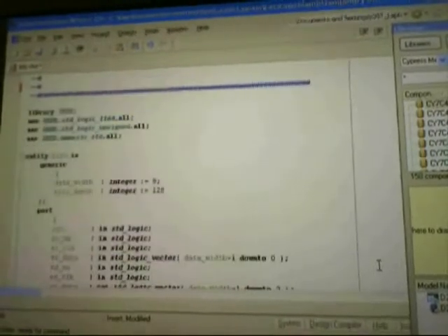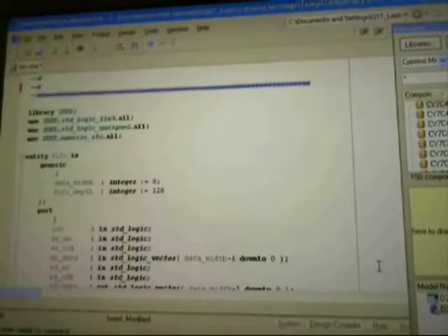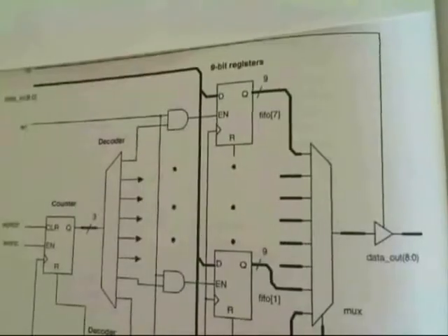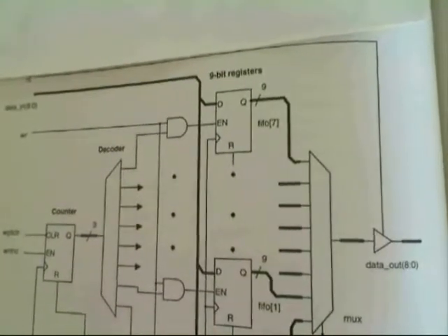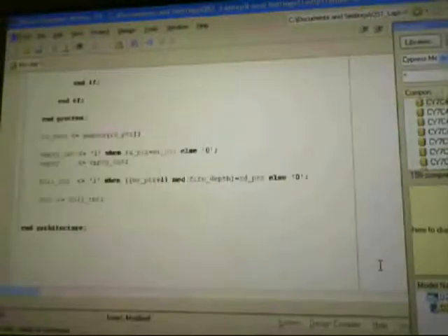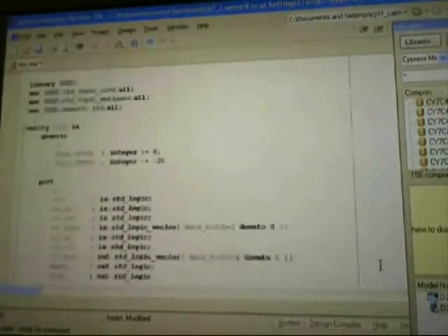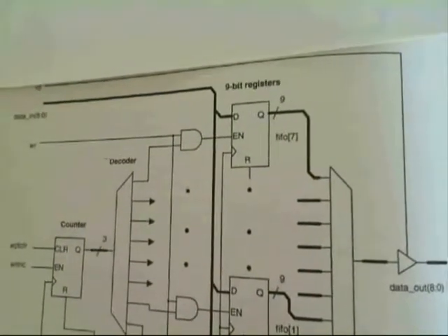The FIFO core provides an optimized solution for all FIFO configurations and delivers 500 MHz performance. It supports FIFO data bits from 1 to 1024 bits, supports independent clock domains. Our sophisticated FIFOs also support error correction, support for packet mode, and support asymmetric ratios, read-to-write port ratios.